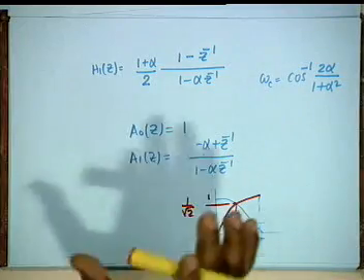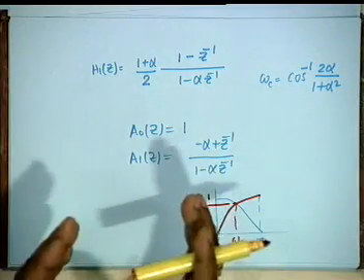If you take a music and separate them by means of these two crossover networks, implemented most economically by a single chip which contains a realization of the first order all pass filter with one delay and one multiplier, then you get a simple digital stereo. Okay. So, this is one of the most used sets in industry. We next consider a magnitude complementary filter.